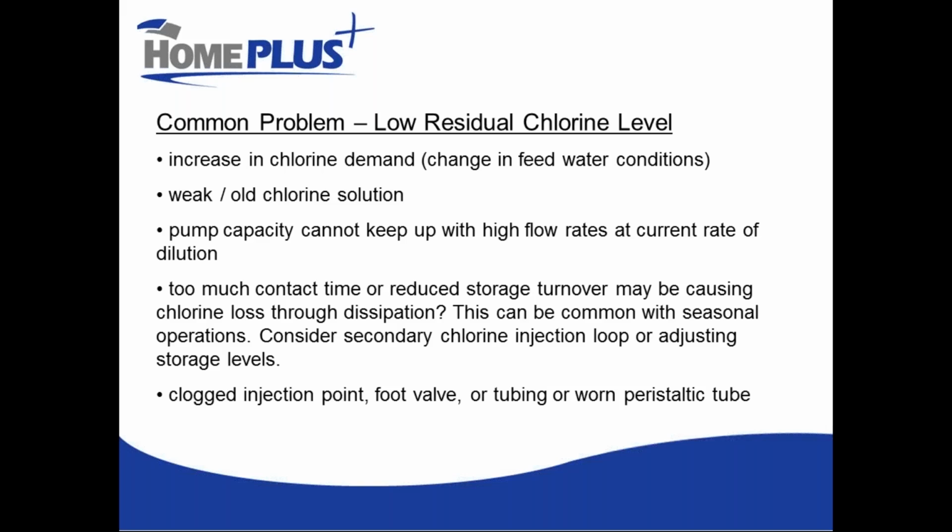We can also have times where chlorine residual drops low because of seasonal factors related to having too much contact time. We think of this in recreational properties, for instance, where water demand is much, much lower in the winter months than in the summer months. In the winter, sometimes there might only be a caretaker on site, but the reservoir is still holding the same amount of water. So the reservoir turnover becomes very, very low, and we have chlorine loss just through dissipation into the air.